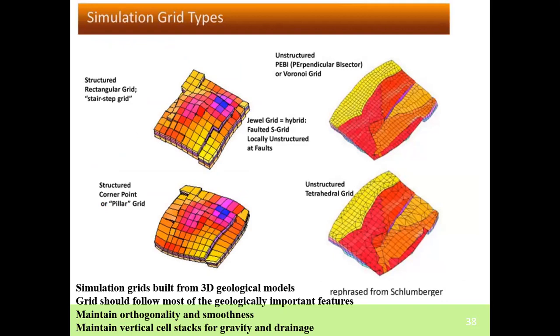So I've included this slide to show you that the gridding is not just blocks or shapes. What you're trying to do is to capture. So for most studies, what you'll be doing is importing a geological model, and then within the simulator environment or within the integrated modeling environment, you will now be coming up with simulator grids. Remember that your simulation grids are to enable you to solve the flow equations across the model.